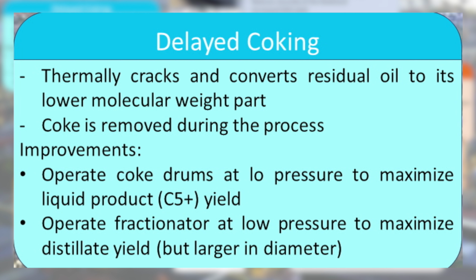Overall, in order to increase refinery yield in residual oil stream processing, operating the coke drum at low pressure is gaining momentum in view of maximizing the liquid product yield. Table 7 shows the effect of low pressure and low recycle on coking yield of a typical feed.